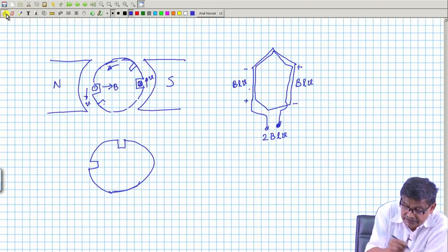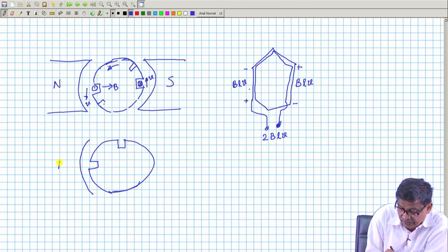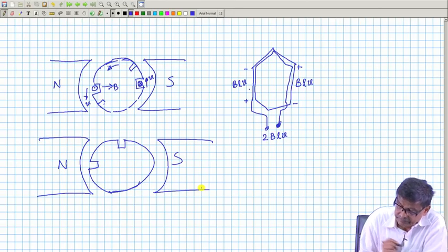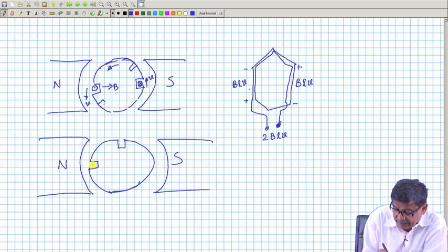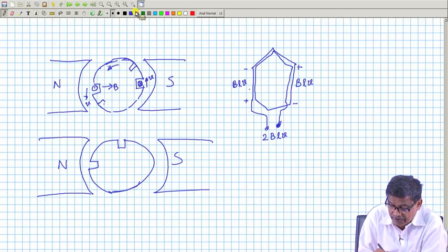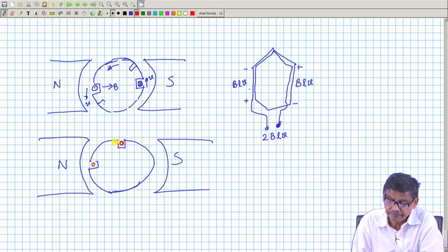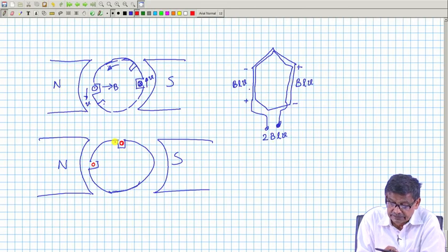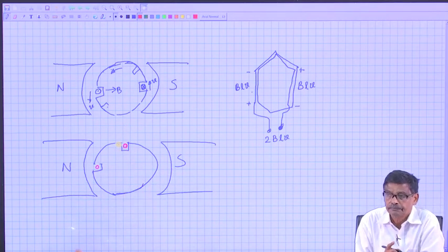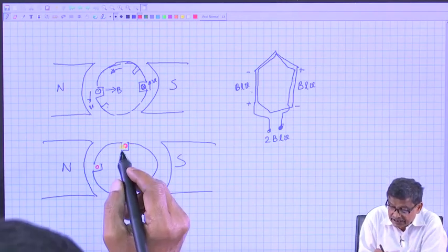And it is a two pole configuration like this, north and this is south, and he places one coil side, he makes a coil such that one coil side is here and its return coil side is here. When this coil side is under the center of the north pole, the other coil side is in the magnetic neutral zone, B is 0 here or tangential to the velocity.